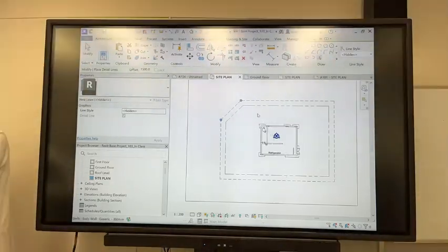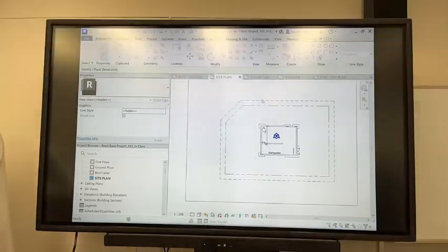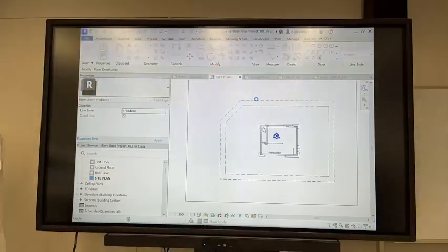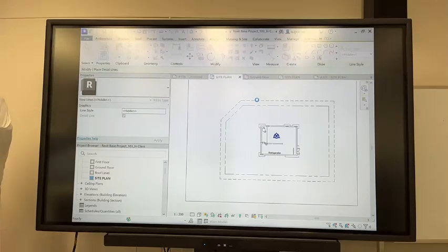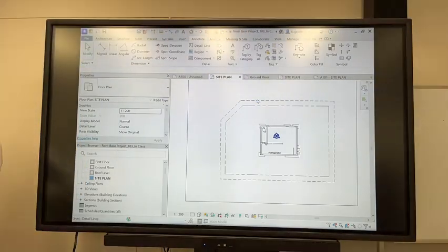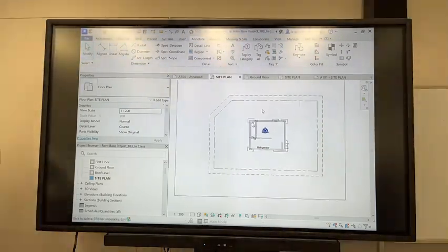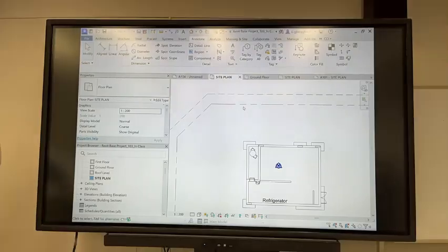So I do it all around. And then when I do my dimensions, I just follow these lines. Either I draw them on the dimensions and then I align them. You can use the align command. Align doesn't work on the dimensions. Maybe not. There's some weird stuff in Revit. So you can do it manually as close as you can.